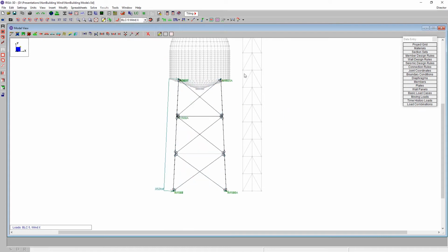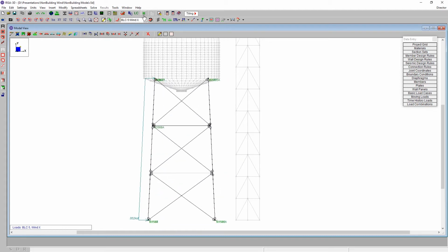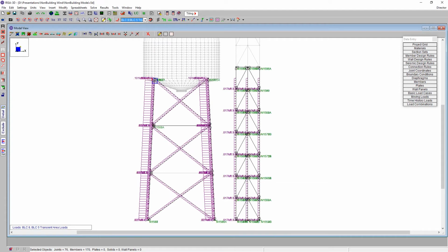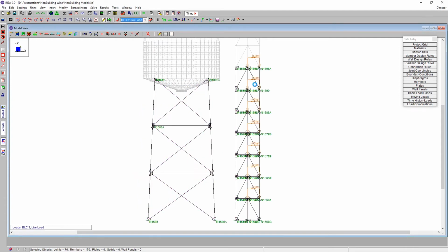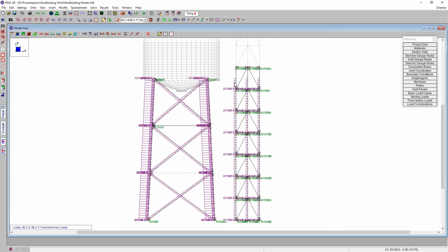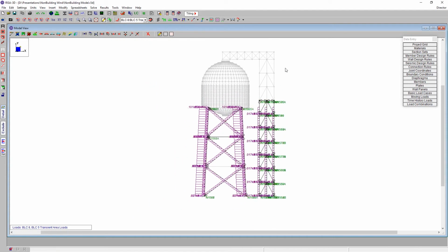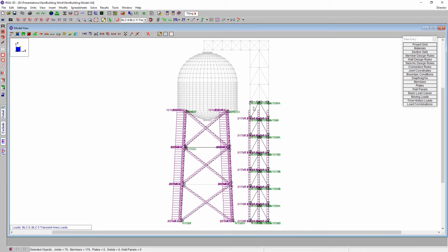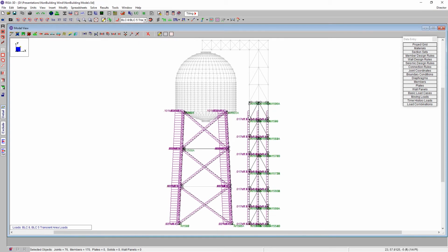We're actually going to have some unintentional wind effect due to this wind X that's going to occur on the tower over here. Note that if I solve and take a look at my transient loads, that wind is actually going to blow right on through the tank legs and hit the tower as well. So here we're seeing this wind load is hitting the tower. If I go ahead and apply the wind load that the tower requires in addition to the wind load that's on the tank here, I'm going to be double dipping, and we certainly don't want that.